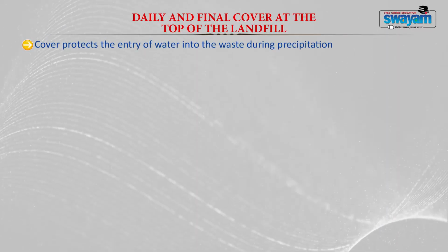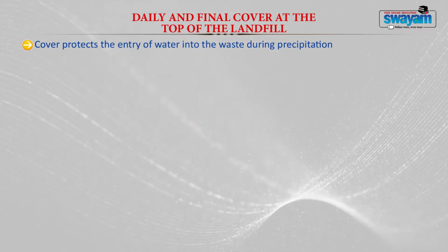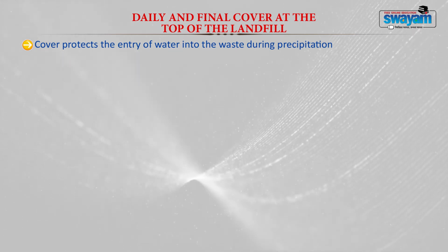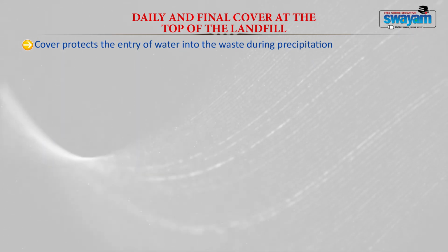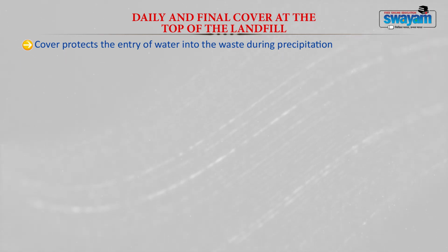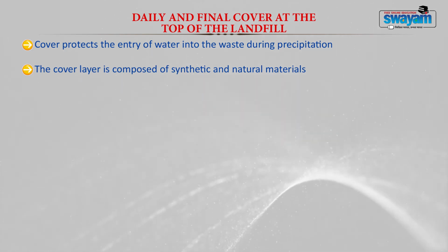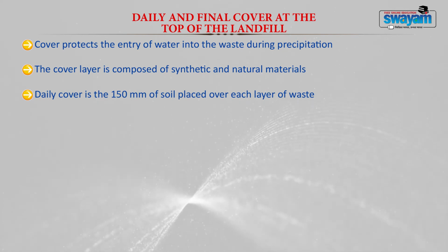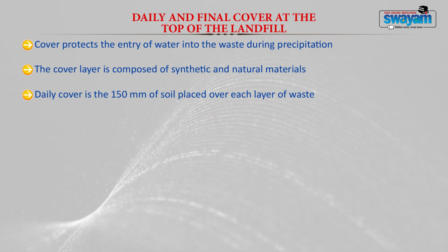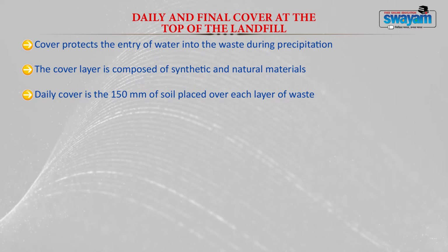Now, the next component is your daily and final cover. Similar to a landfill process, after you load the waste, it should be covered with a cover material, or after every day's loading you should also cover it with a cover material. Now, the cover generally prevents the entry of water into the waste during rainfall or any other form of precipitation. They also keep animals away from the waste material. Generally the cover layer is composed of synthetic and natural materials, and this cover layer extends to a level of 150 mm of soil which is placed over each layer of waste and at the end also.